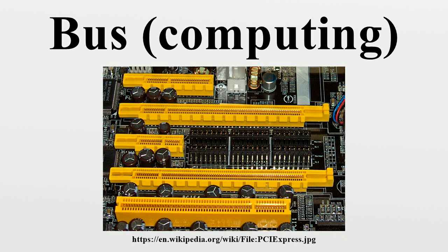These simple bus systems had a serious drawback when used for general-purpose computers. All the equipment on the bus had to talk at the same speed, as it shared a single clock. Increasing the speed of the CPU becomes harder, because the speed of all the devices must increase as well. When it is not practical or economical to have all devices as fast as the CPU, the CPU must either enter a wait state, or work at a slower clock frequency temporarily, to talk to other devices in the computer. While acceptable in embedded systems, this problem was not tolerated for long in general-purpose, user-expandable computers.